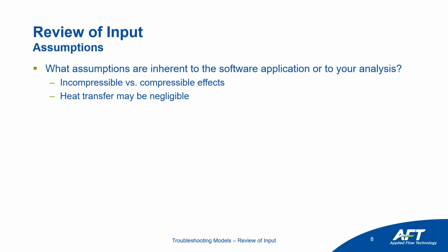Heat transfer may be negligible. So this might be a harder sell as an assumption when you have compressible fluids, where heat in might expand the fluid, or heat out might de-expand or compress the fluid a bit more. That'll change how fast your fluid is flowing, the losses that it sees, impacting the pressure. And again, all those equations of state are all related, but it's an option. You can simplify your model, eliminate heat transfer, and see if there are any consequences to your results.